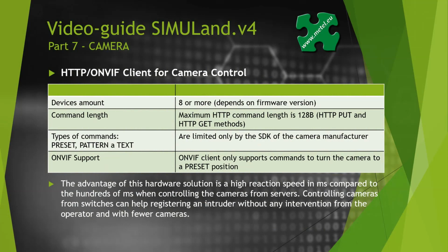Command types such as turn to preset, start pattern or show text are limited only by the SDK from the camera manufacturer. The basic version of the ONVIF client only supports preset camera position commands. The advantage of this hardware solution is the high response rate in milliseconds, in comparison with hundreds of milliseconds when cameras are controlled from servers.